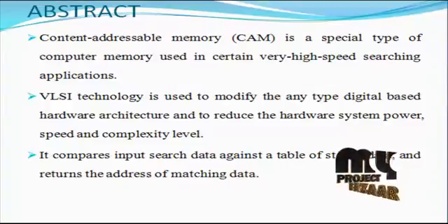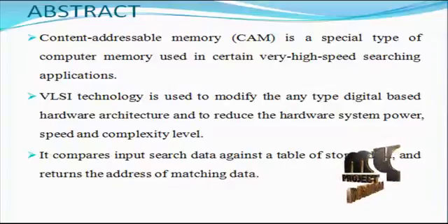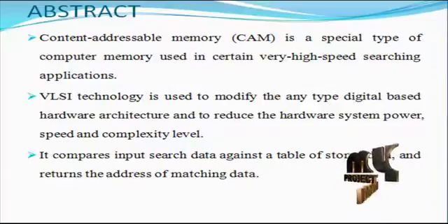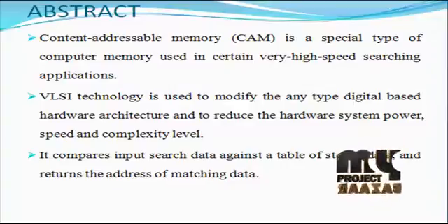We propose a low power content addressable memory employing a new algorithm for associating the input tag and the corresponding address of the output data. The proposed architecture is based on the recently developed sparse clustered network using binary connections that eliminates most of the parallel comparisons performed during a search.